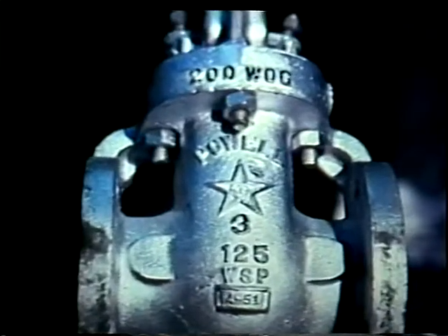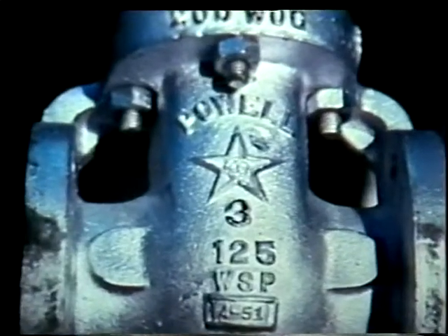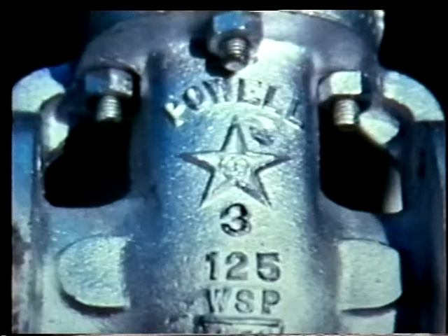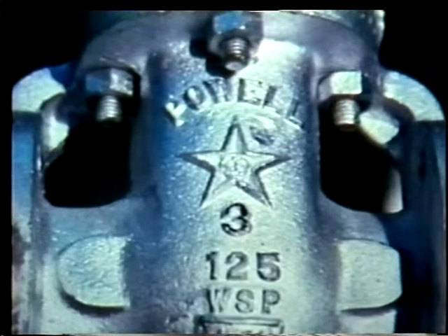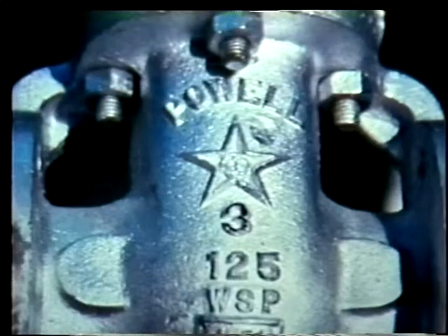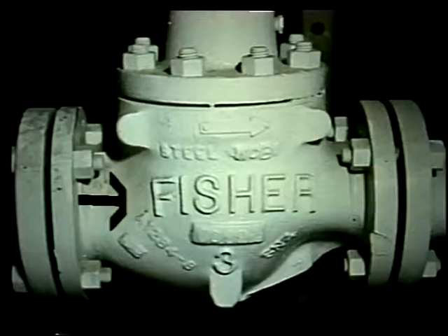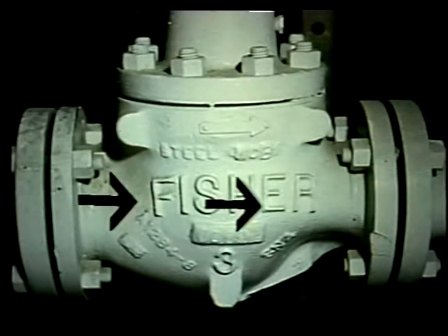You see here bridge wall markings. They provide very useful information. They indicate how the internal parts of the valve are arranged. By knowing how the parts are arranged inside, you'll be able to tell how the disc closes on the seat of the valve. Bridge wall markings on this valve show that flow comes in from the left, and then passes through the open area of the seat to come through this outlet.